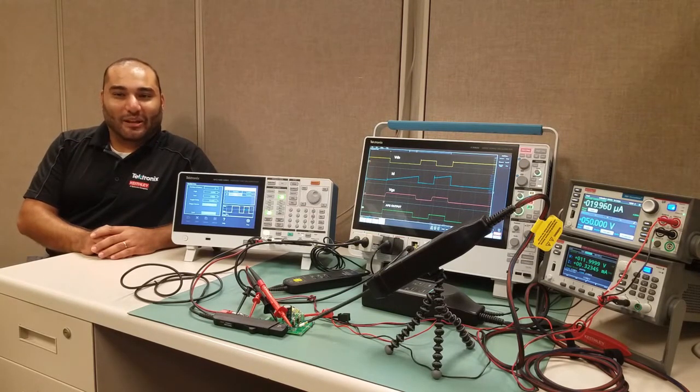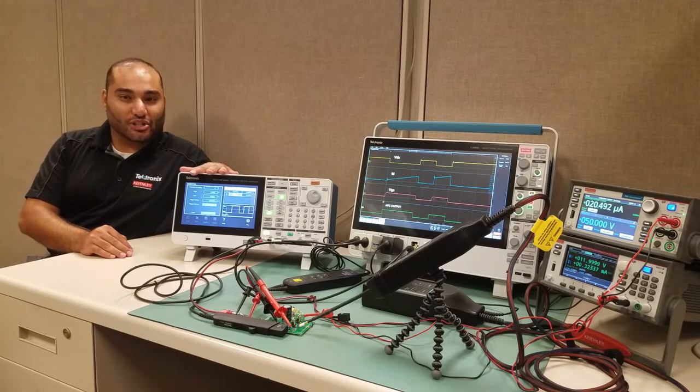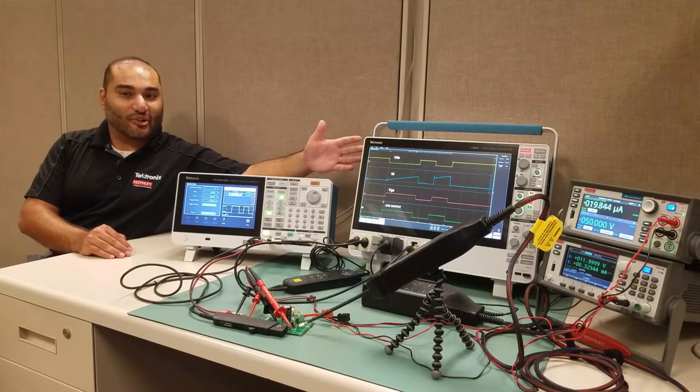Today, I'll explain what the double pulse test is and why engineers perform it. I'll show you how to use the double pulse application on a Tektronix arbitrary function generator, AFG31000, to set up your pulses in less than a minute. We will also show measurements on a Tektronix Oscilloscope MSO5 to measure our parameters.